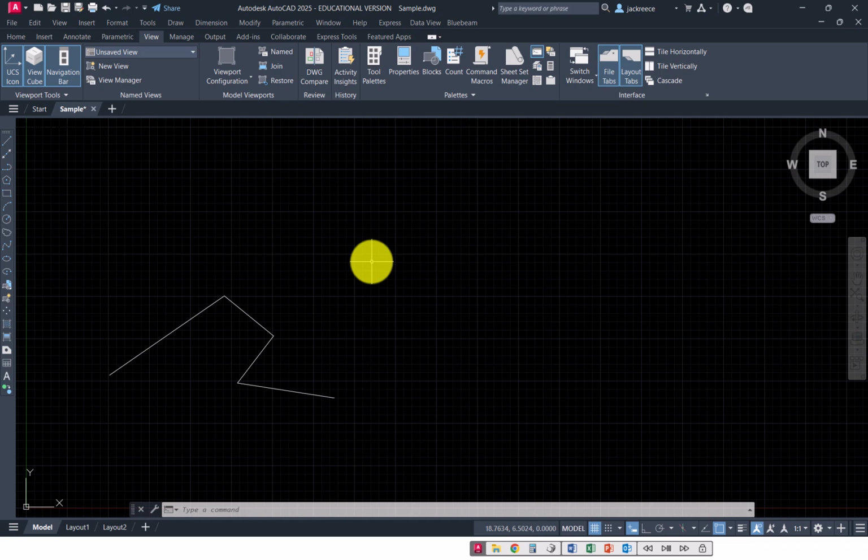And every command that AutoCAD has, if there's an option, it's going to ask you something in the command line and in dynamic input of what you're supposed to do next or what it wants. If you're going to draw a circle, it asks you for the center point of the circle and then the radius of the circle.